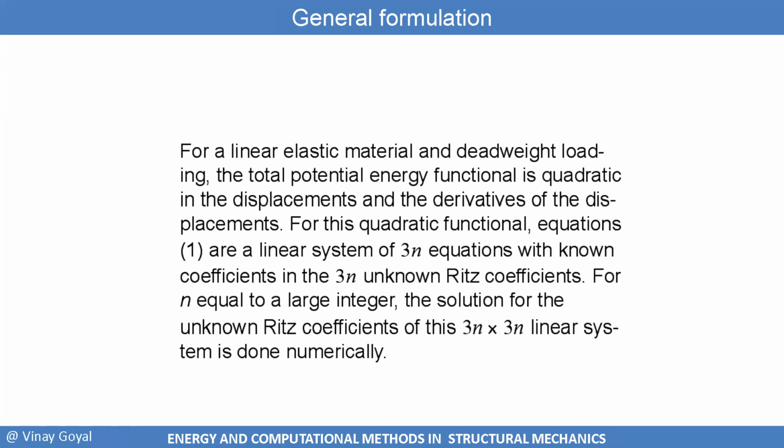For linear elastic material and dead weight loading, the total potential energy functional is quadratic in the deflections. For this quadratic functional, you will have three n equations, three n unknown Ritz coefficients, and you'll be able to then solve the problem.